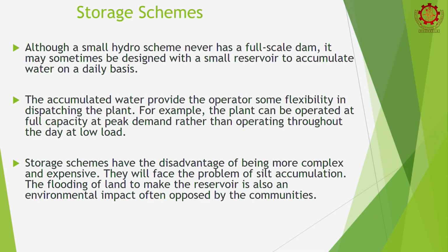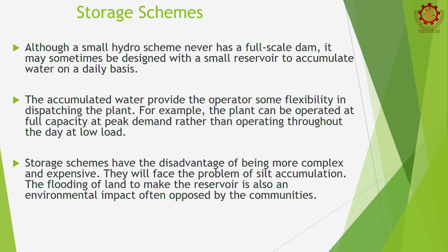Therefore, either you have to remove silt or otherwise your water retention will be lower and lower. This is especially happening because of the lot of agricultural activities in these areas, which let a lot of silt flow and end up in the reservoir bottoms. So, these are negative impacts of large hydro.